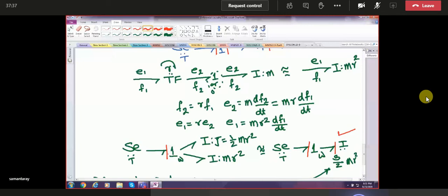So basically, okay, there was a loss of time constant. Conversion of rotational motion to linear motion or linear motion to rotational motion has to take place in some time. If that time is missing, that time is coming through that frictional resistance. If that time is missing, then you cannot model those two things as separate degrees of freedom. You have to merge them and make them a single degree of freedom. Otherwise, you have to include the resistance in the model.